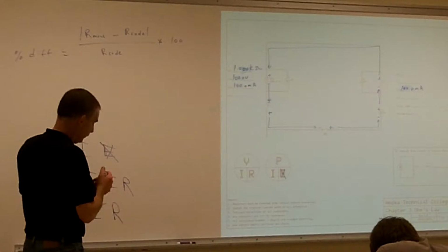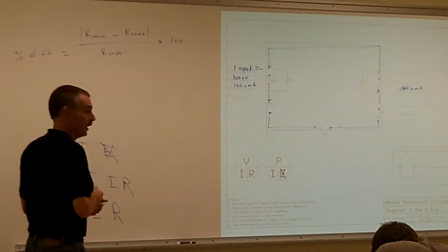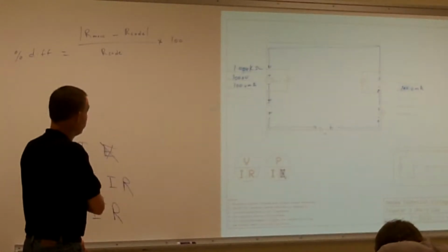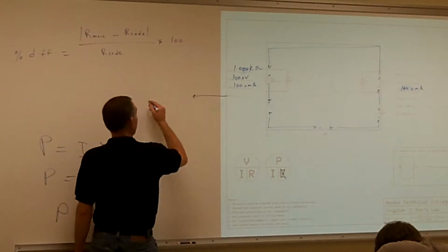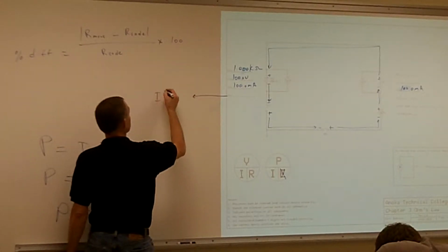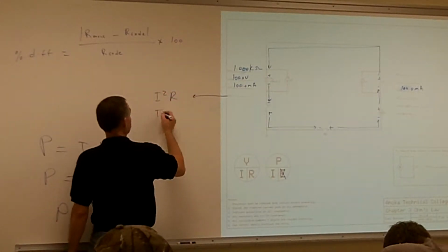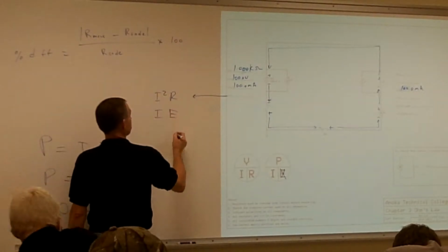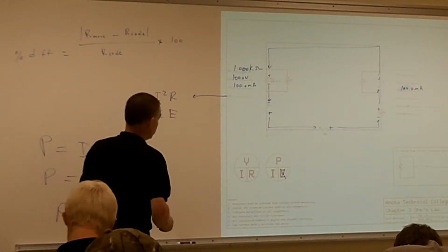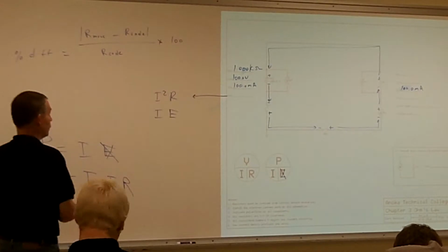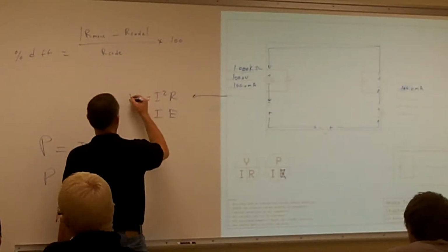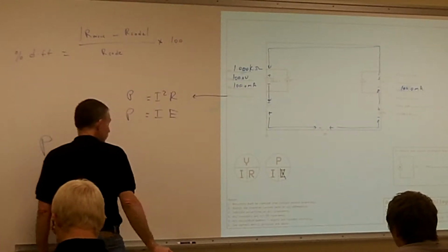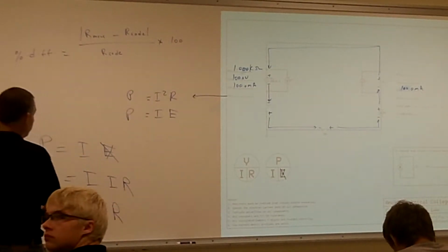It's also good to figure out your power. We might as well figure out our power. What would I use to calculate my power? I squared R would work, or I times E would work. Either one of those would work, and either one equals power. It all depends on what information you have.